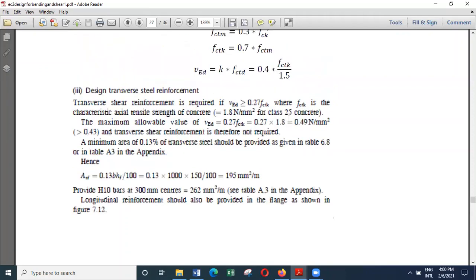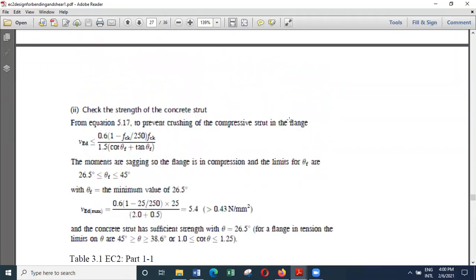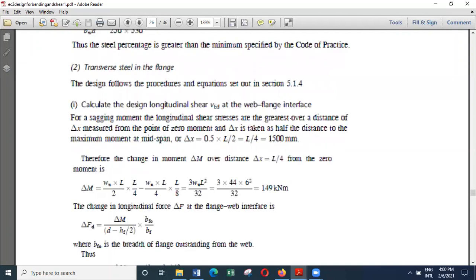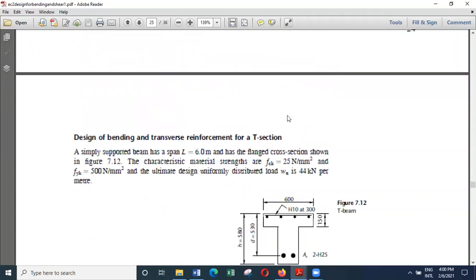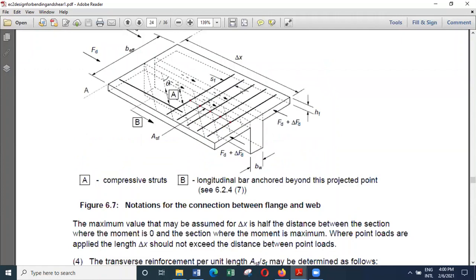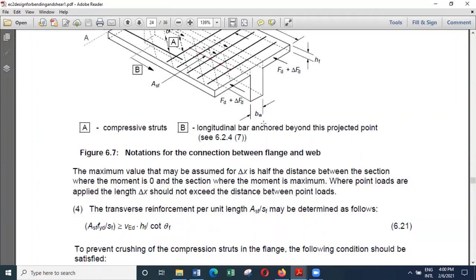So, any questions on that? You might not generally be performing this calculation, but this particular calculation to determine whether we need extra reinforcement here to resist the shear between flange and web has to be performed, and this may be particularly important in the case of foundations, inverted T-type foundations, because the loads will be higher. So any questions on this, please?